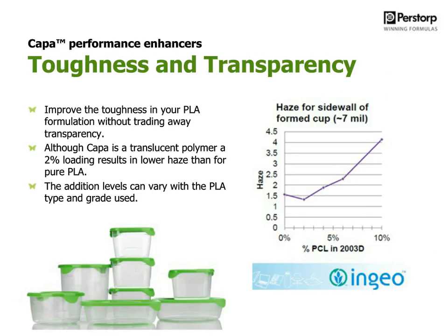We have also looked into what happens if you add different levels of polycaprolactone in a transparent polymer. Polycaprolactone is translucent and milky when you look at it, and that might limit the use in applications where you need to have a transparent appearance. But at the same point, we have seen that by adding lower levels, you can still modify the mechanical properties and still maintain the transparency, which is very interesting for many applications in the serviceware industry.